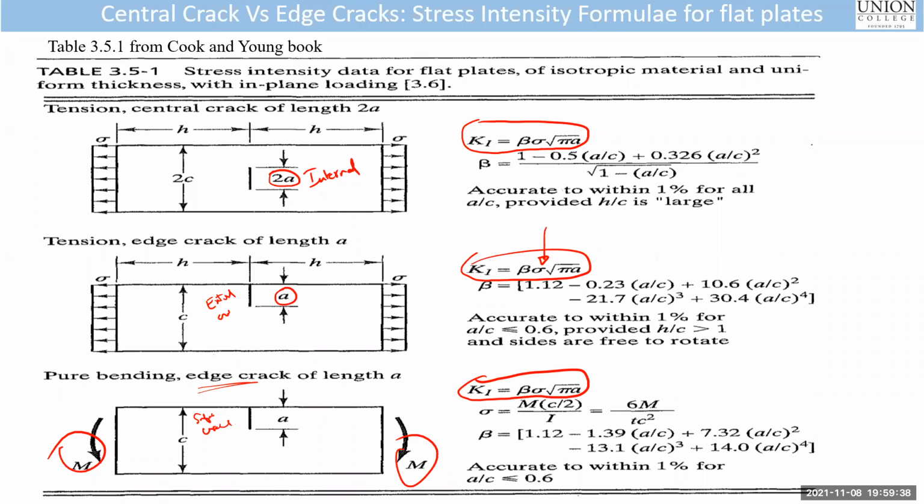No, bending applies tensile and compressive, right? So imagine, I don't have the swans today, so imagine I'm bending it this way in a frowny shape. If I imagine lines here, the top lines are stretching. There is tension on the top fibers. The bottom fibers are going to shrink, so there is compression. So bending moment is nothing but you have tension somewhere. So if you have a bending moment in frowning shape, you have tension like this, and the bottom surface has compression like this, right?